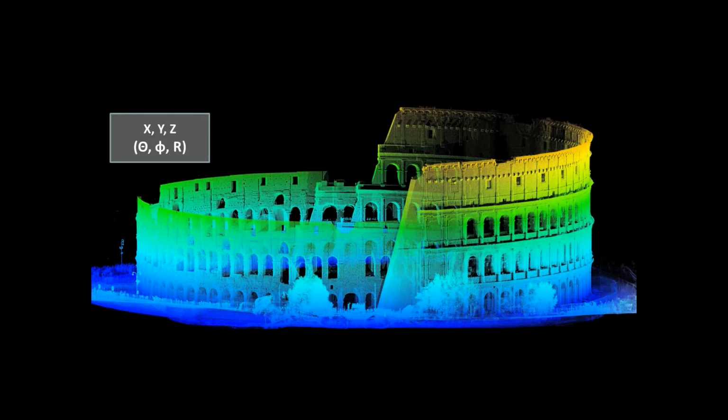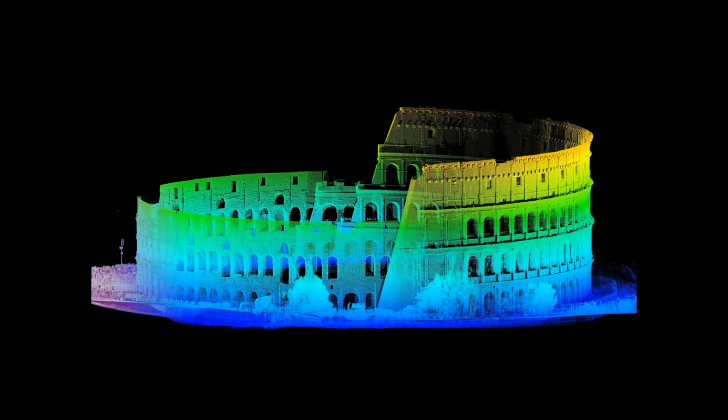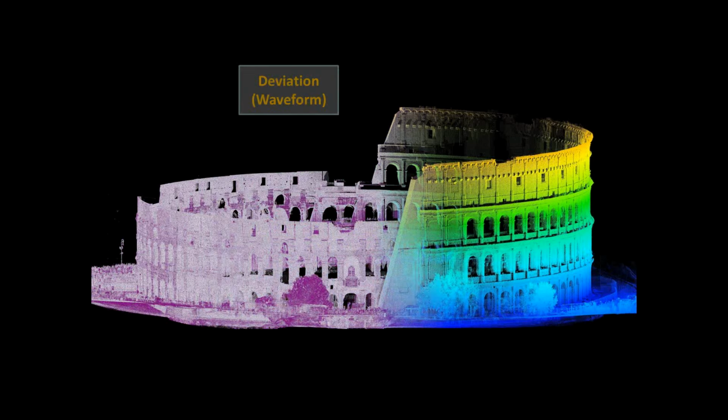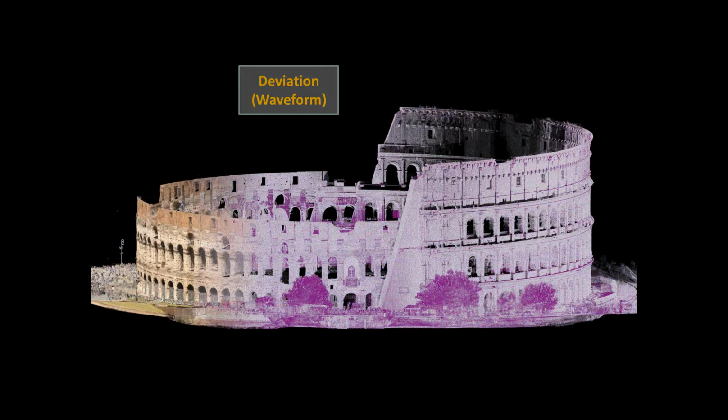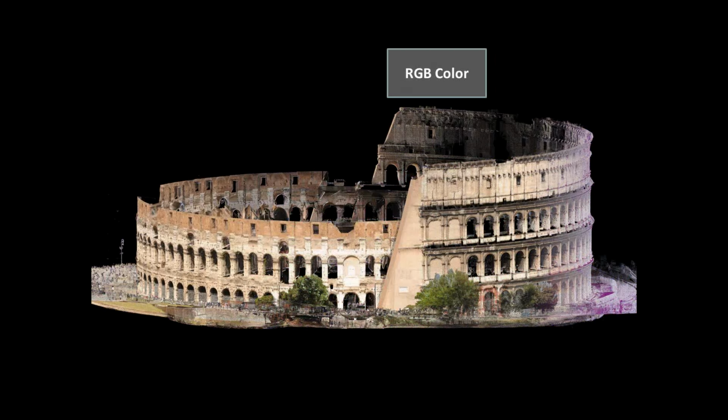From that digital amplitude, we extract distance, and we of course are measuring theta and phi. That's what you see on the bottom there, theta, phi, range. It's the two angles and the distance. So you have a 3D point cloud. This is by height, so we have a 3D attribute. Then we have the deviation attribute. Again, Tan will show you how this is useful in the real world in a minute. That's shown here. Of course, if you have a camera, then you have RGB or true color as well.